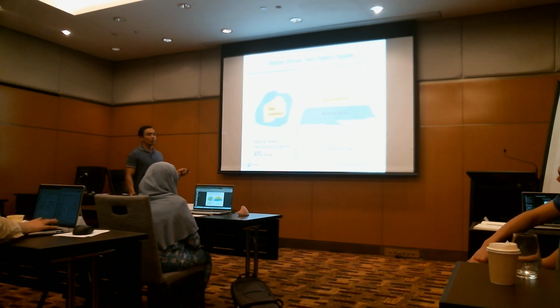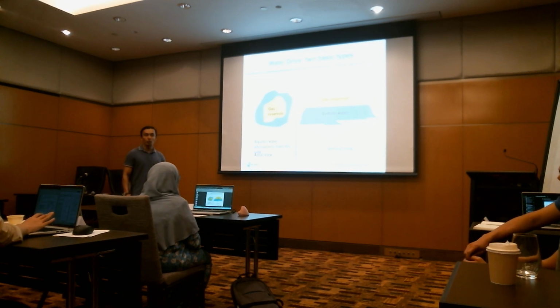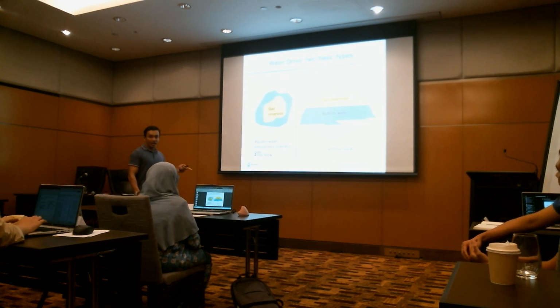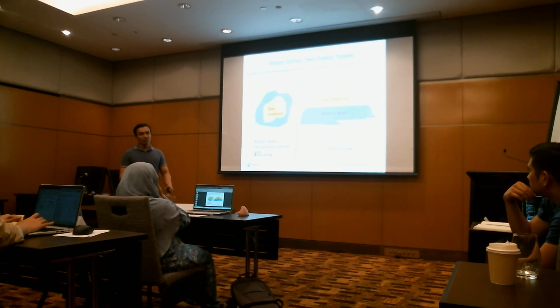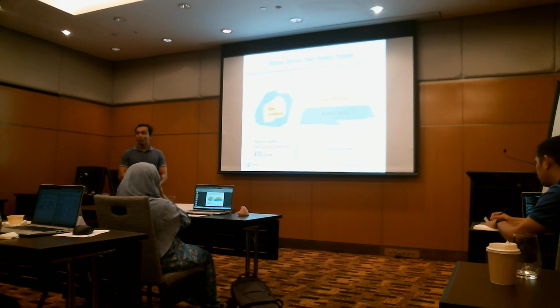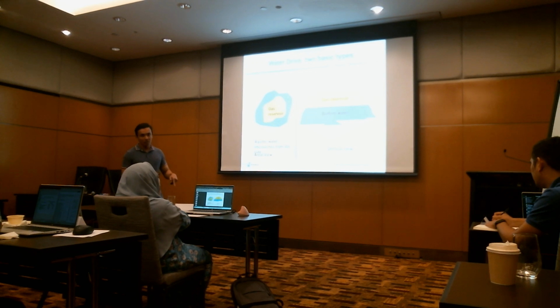So that's why in a gas reservoir without water, you expect very high recovery, but of course it is limited by the landing pressure. Another aspect is your facilities. For the gas case, it's pretty much driven by your facilities. The lower the landing pressure, the higher the delta P, and the more you can produce. Landing pressure is at the facilities.